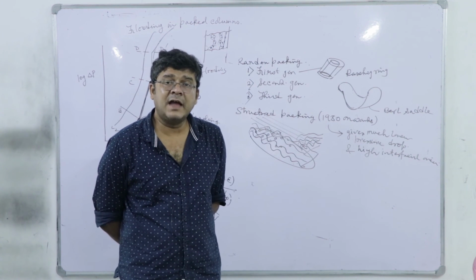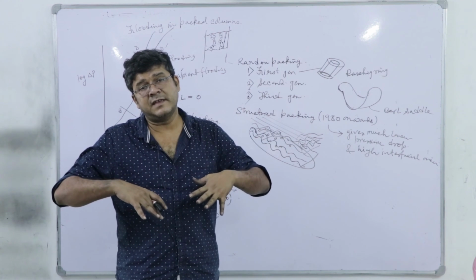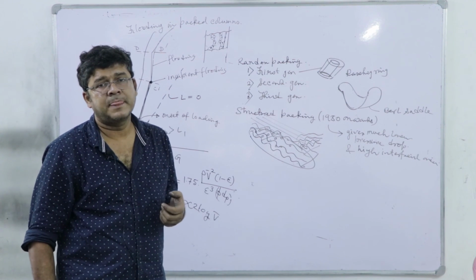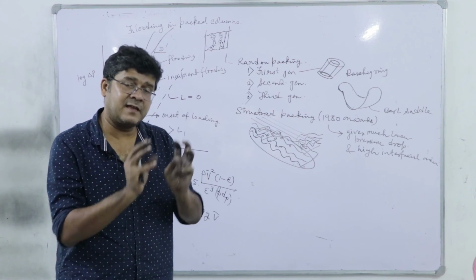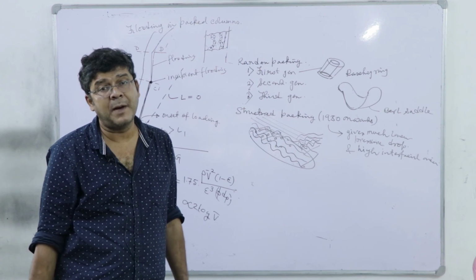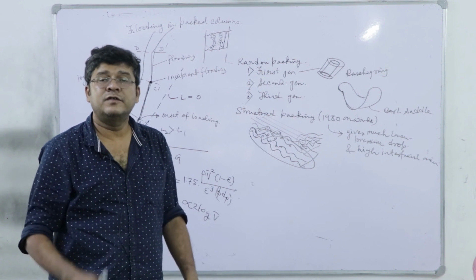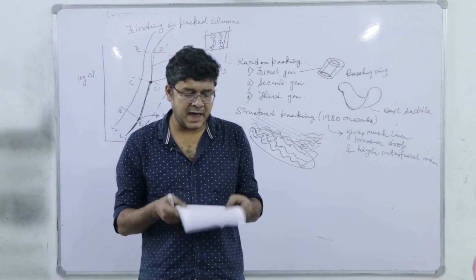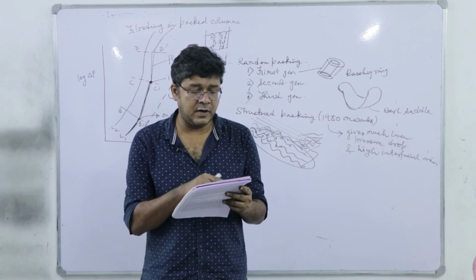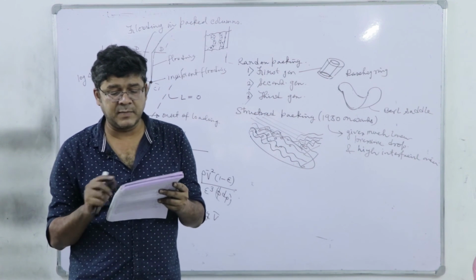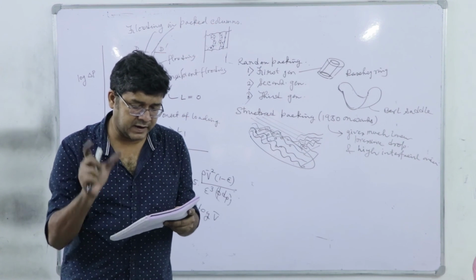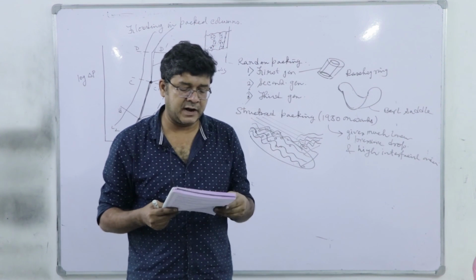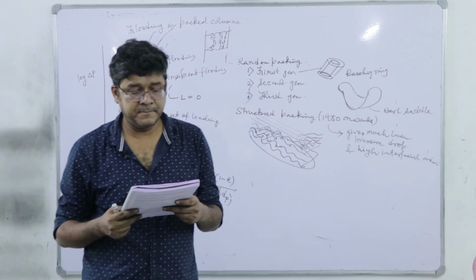But if we have flooding in packed bed, the liquid starts accumulating in the bed. The liquid will fill up the void space in this packing, right, and through that void space the gas will be forming bubbles, because it has to pass through the pool of liquid that has accumulated. So, there will be a severe drop of mass transfer efficiency, and that is why flooding in packed bed is sometimes defined as a region of rapidly increasing pressure drop with simultaneous loss of mass transfer efficiency. This is a description of flooding as proposed by Bravo and Fair, right.